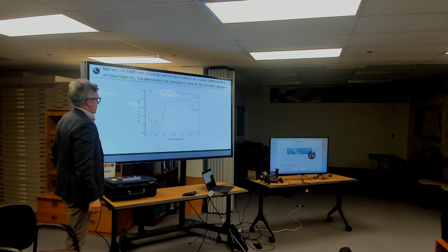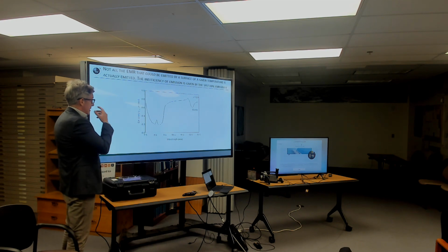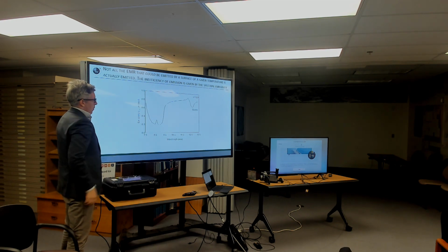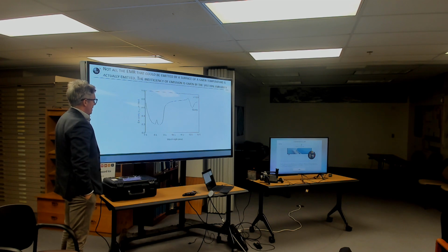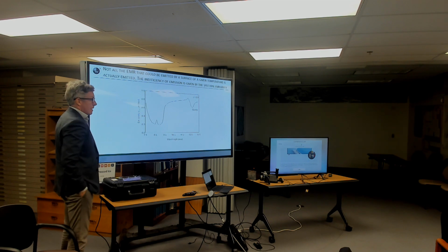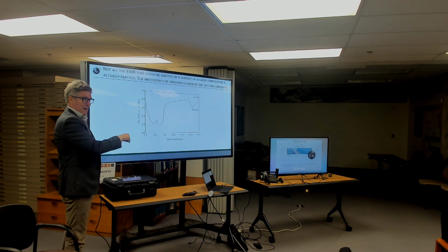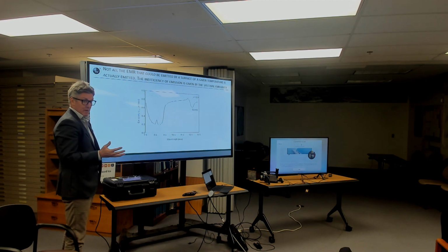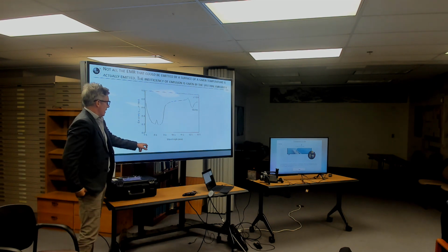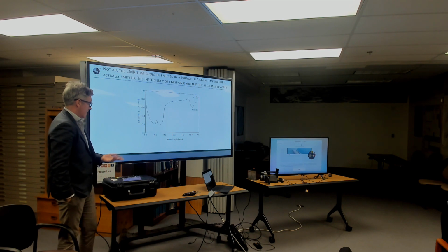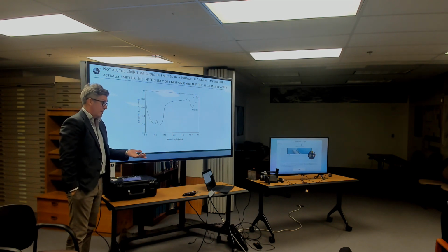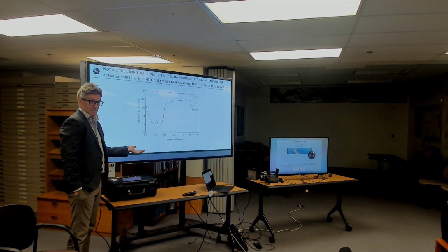If we look at quartz, we can say a few things. At 12.5 microns, quartz exhibits near black body behavior. At 12.5 microns, quartz emits 90% of the light it could if it were a black body, so it's 90% efficient relative to the black body standard. We can also say that at 9 microns, quartz's capability to radiate is only 20% of a black body at the same temperature.